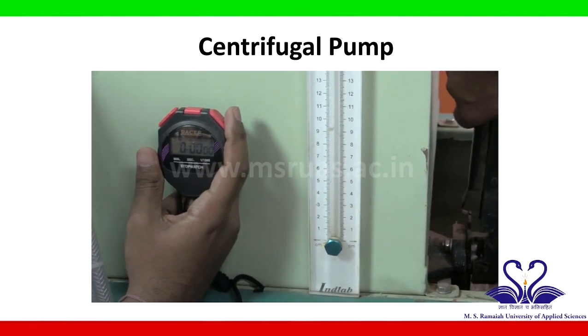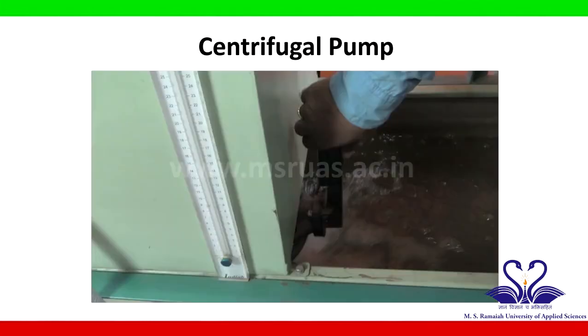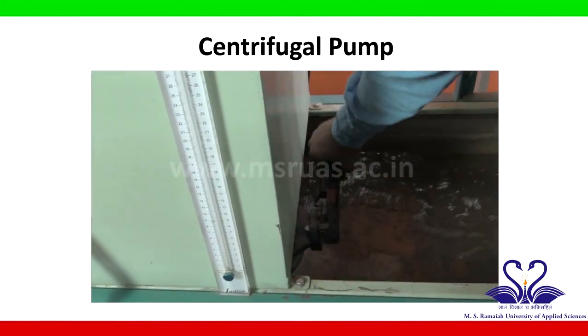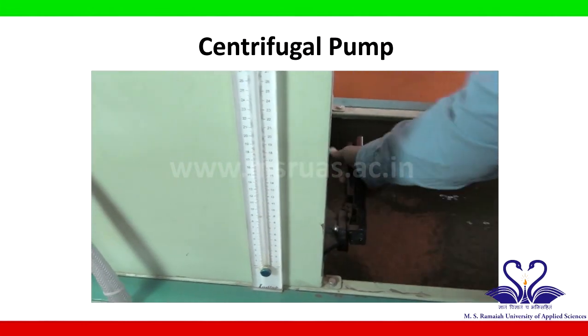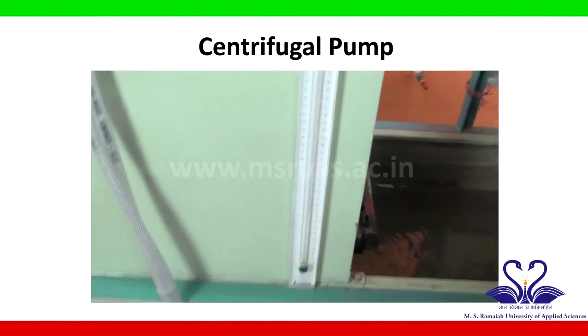In order to calculate the actual discharge of the water, we close the butterfly valve of the collecting tank and note down the time required for the rise of water from 5 to 20 centimeters.